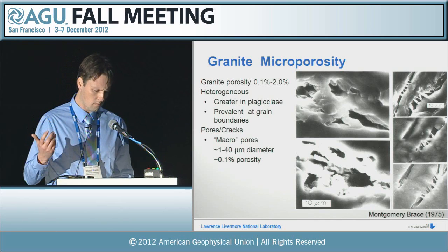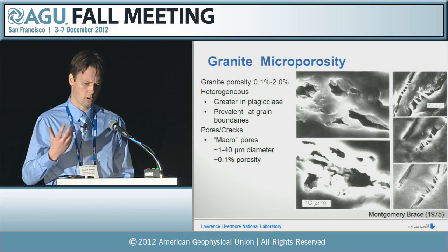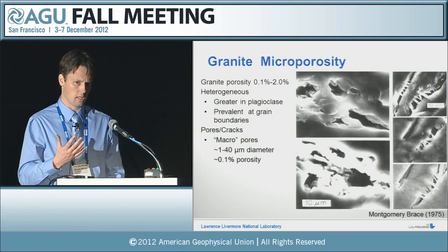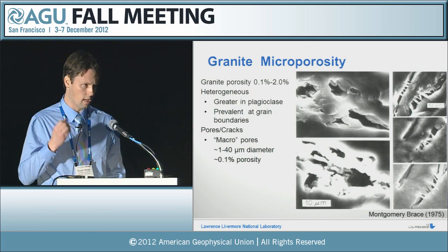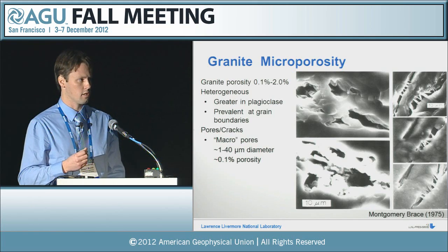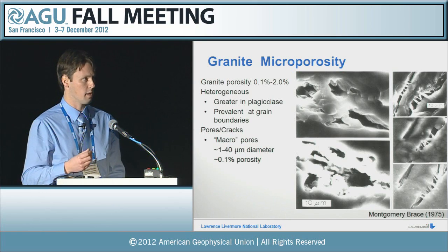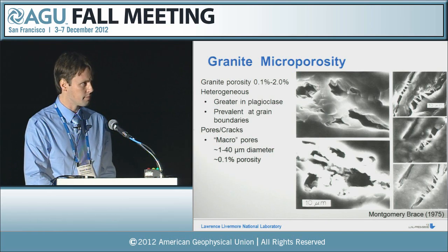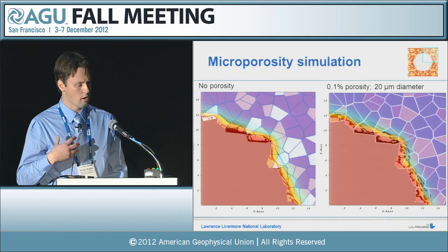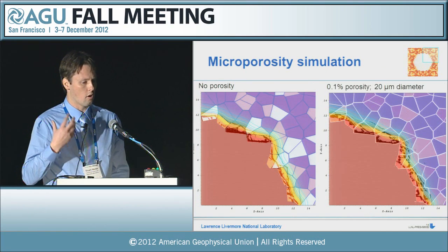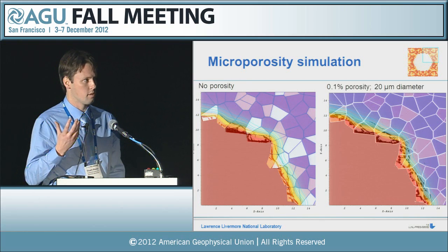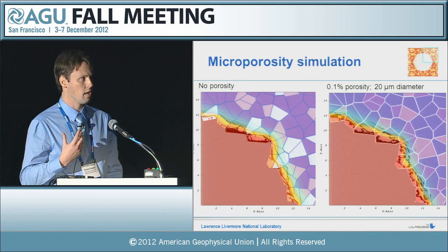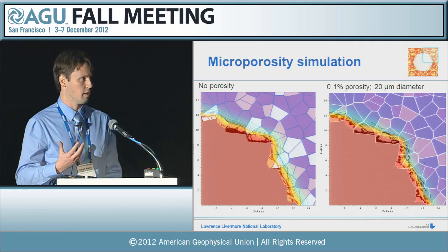What's more, it's not just the porosity that drives this vapor-driven spallation, it's the low permeability. It's the ability to build up that vapor pressure that assists in creating spalls. And granite has that in spades, obviously. So in order to see what effect this would have, we ran a series of microstructural simulations where we introduced porosity into the granite assembly.